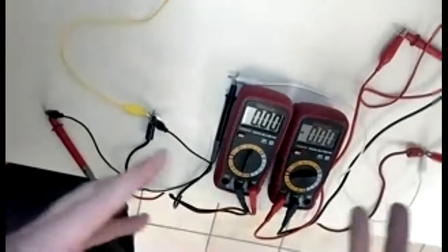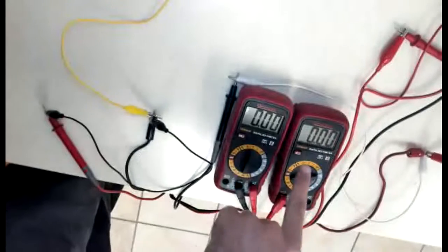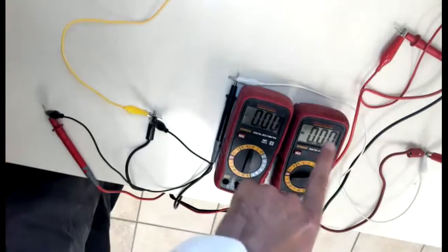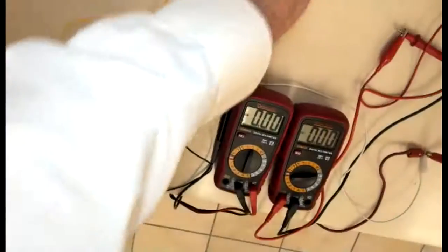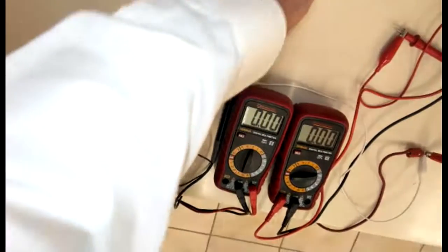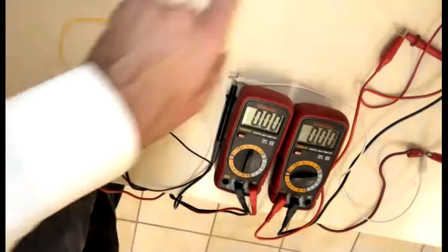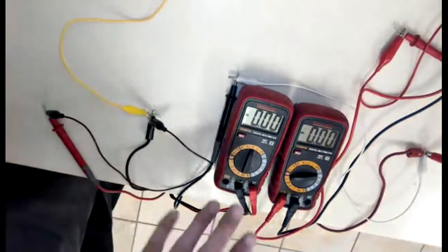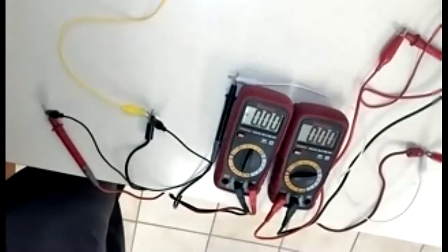It's really tough to see the different connecting leads, but I basically have coming out of the wall, the source of EMF, going into my ammeter, right? Because this has to be part of the circuit. And then it comes out of the ammeter into my resistor that's out of the frame right now. Okay, and then out of the resistor back into the wall. The voltmeter is wired up in parallel. So voltmeters have to be wired in parallel.